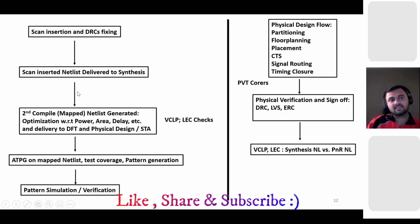The synthesis team will take your netlist and synthesize it again, and here they will do lots of optimization. In the first compile, they will not do so much optimization, but in the second, once your scan is inserted, they will do power optimization, area optimization, and delay optimization. There are so many optimizations in the synthesis step. Once they get the scan inserted netlist from you, they will synthesize and optimize it, and again deliver it to DFT and the physical design or static timing analysis team.